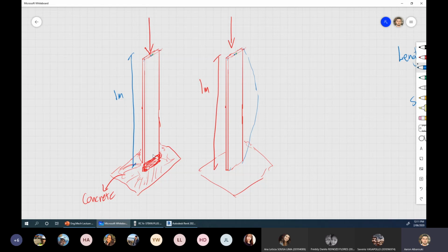So he's saying it still will buckle. Yep, perfect. That's 100%. So Fabio is saying, even if you do that, I still think this will buckle because still the slenderness ratio is very high. So the length to the width is large. I agree. But what other observations can you tell me? Anyone else have a different idea on this?